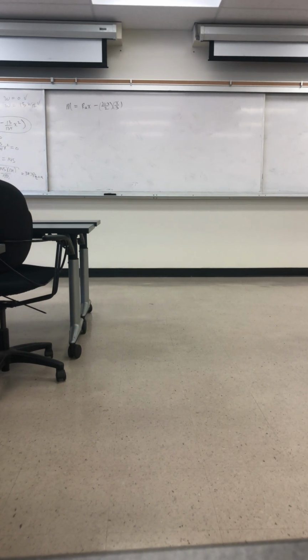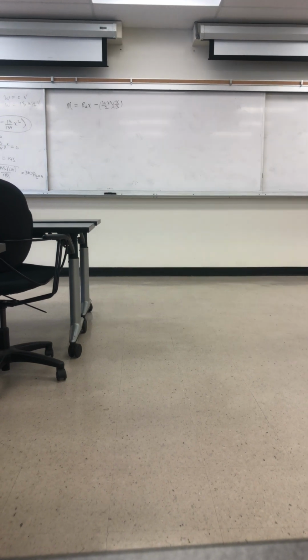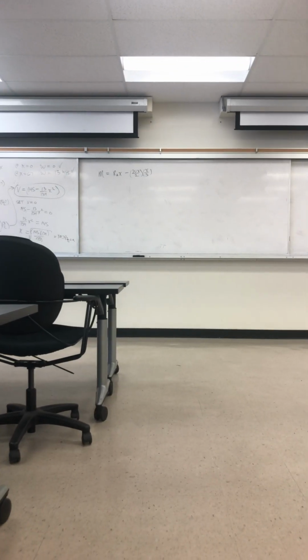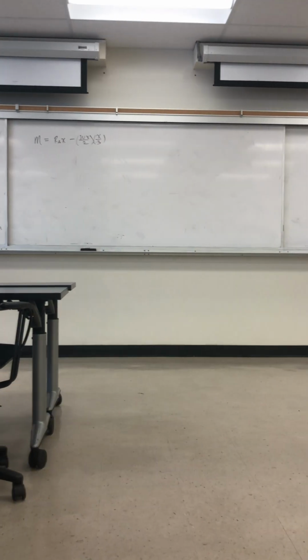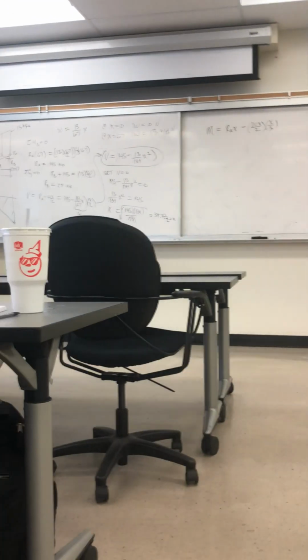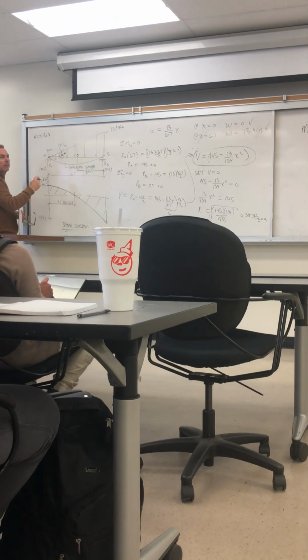Here for the moment, we're going out a certain distance x. So we're saying that the moment is this reaction A multiplied by x. That's the moment contribution from the vertical reaction at the left. And then that's clockwise, and then we're going to subtract the moment associated with this little triangle here up to that point x, any point x, okay?